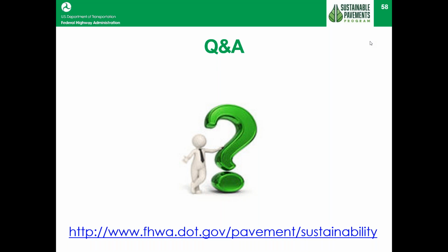Right. And certainly a lot of these different pavements and a lot of these different distresses have some critical values associated with them. For example, I know on concrete pavements, we often consider faulting of somewhere around the order of 1/8 of an inch or 1/10 of an inch as being something that's critical, that requires some kind of treatment. And I think in the literature, you'll find a lot of those types of general guidelines and general thresholds.